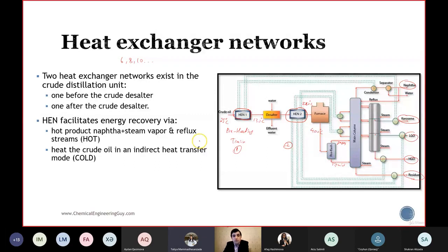If you want to use one heat exchanger, that exchanger will be very big, first of all. All the heat exchangers will have the same size because the crude passes through all of them. But you don't have so much heat in one stream. Where will you take that from? Why does it pass through different heat exchangers?